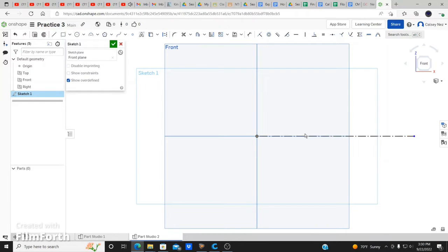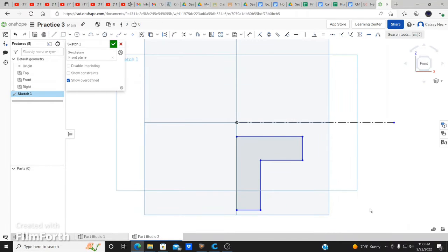So there's no dimension. What I'm gonna do is create my shape down here, but I'm gonna go away from that hidden line. Go right here on the vertical of that point and go straight down. Go to my right, go up, go to my right, go up. I'm gonna match up my height from here. It's gonna activate that one. Click this one on this horizontal, and there we go.